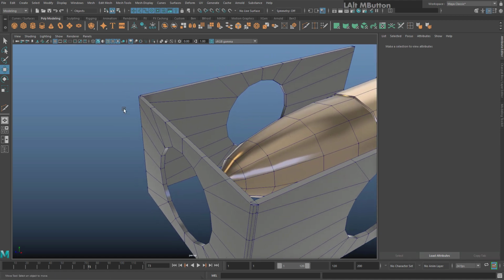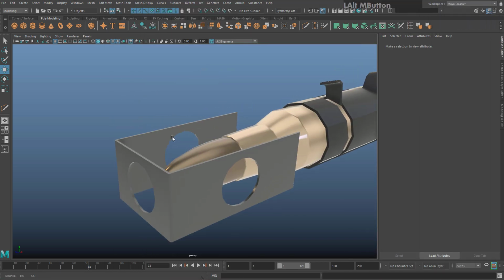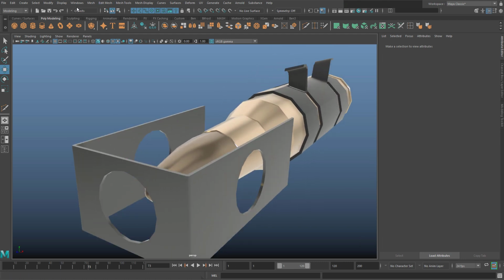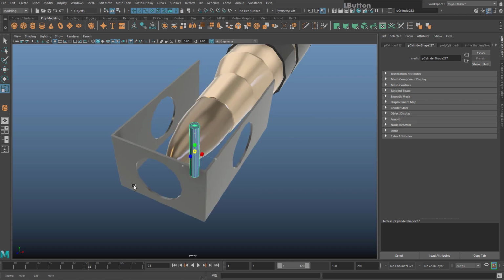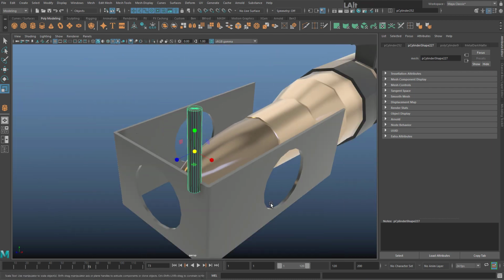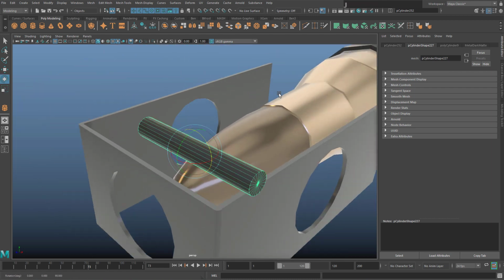Now we need to create a very small cylinder to go on the top of this. So the top and bottom of this have a cylindrical effect, sort of grill to them, and this is one of the last steps that we need to create, and from here on it's duplicating. So go to create a new cylinder, move it roughly into position, resize it down, right click, assign existing material, your same material as this bit, hold E, hold down J for rotate, and rotate the cylinder like that.